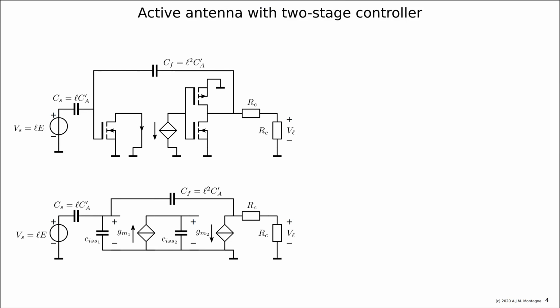So this is the small signal diagram of the circuit. If we use the first stage as a CS stage, which is shorted, and the drain gate capacitance is solely included in the input capacitance. So there's no connection between the drain and the gate in a small signal diagram. That is often justified, definitely in the case of a shorted stage, because then the Miller effect is not present. And secondly, the gate drain capacitance is much smaller usually than the input capacitance.